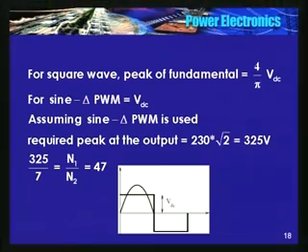It is VDC itself, for modulation index equal to 1. For modulation index equal to 1, the peak of the sine wave is the input voltage itself. Please note, in a half bridge I said it is VDC by 2. In a full bridge it is VDC.